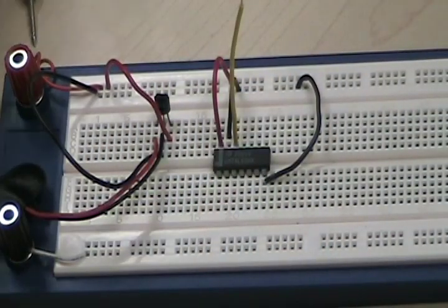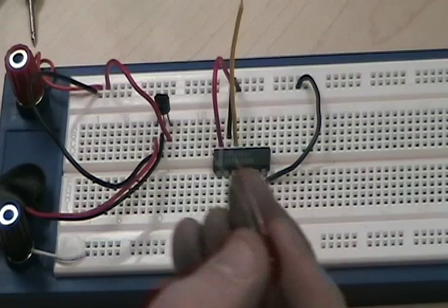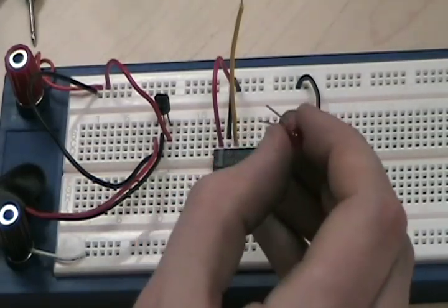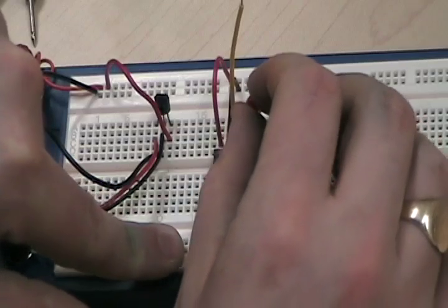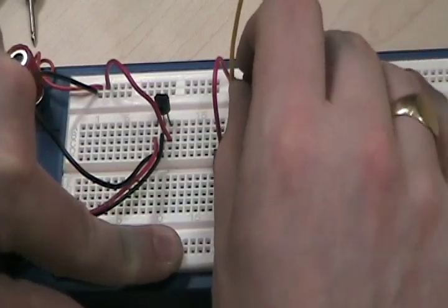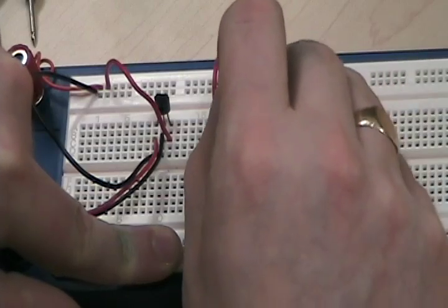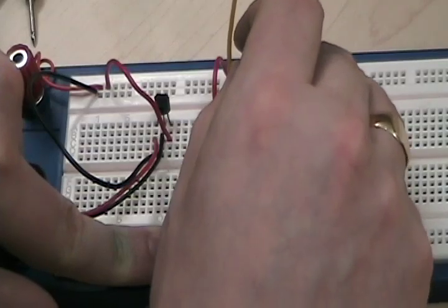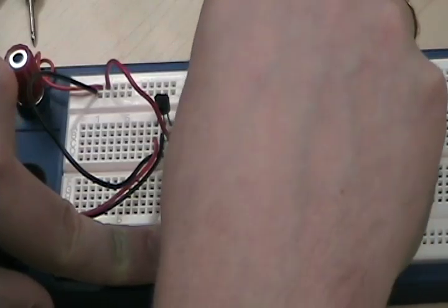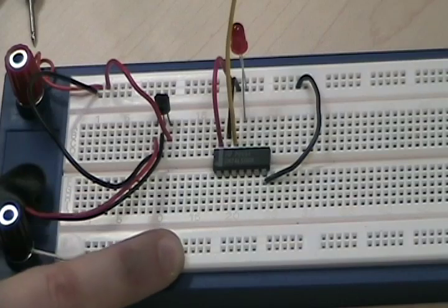We're going to take what's called an LED, a light emitting diode, and I'll tell you more about light emitting diodes a little bit later, not in this lab, but in another one. Light emitting diodes can only be placed in one way, or else it won't work. It has to be placed with the anode connected to the positive power supply and the cathode to ground. You won't have to understand this now because we'll talk about it later. So we put the anode in the output line, and the cathode, the negative, into the ground line.